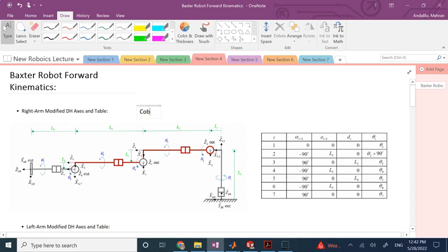And why is it called like that? Because really it was supposed to be trained by humans, and humans really take the robot arm and move it to any configuration, any pose that they want, and then to another one and do some task with it. And the robot is supposed to keep in mind all of these configurations and how it went from one to the other, and then be able to repeat it, right? So you could then train this robot, add a gripper or anything to the end effector, to the last link, the joint, the frame 7, and perform any task that you want.